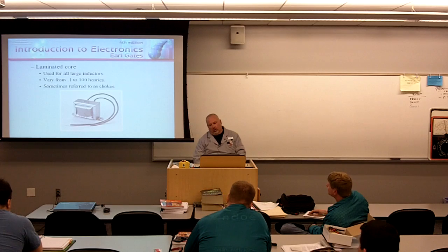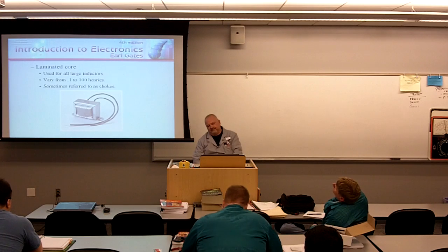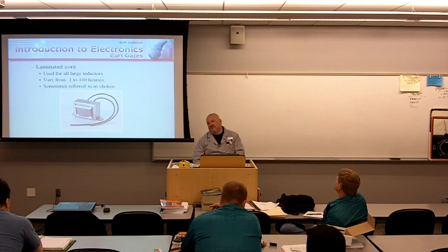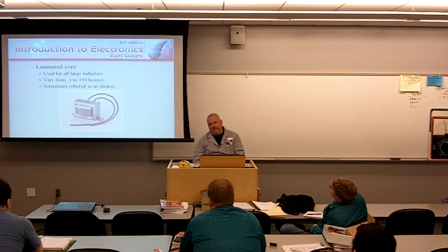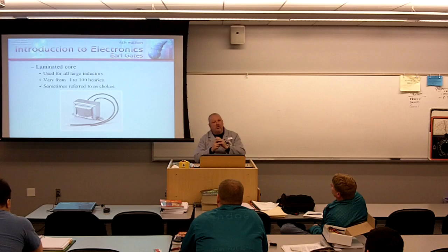This is a laminated core. And again, if you didn't know any better, you'd think it was a transformer. We know it's an inductor because there are only 2 wires coming out of it, and the top is stamped 4.5 Henrys, 4.5H. These can vary from 0.1 Henrys all the way up to 100 Henrys. This is also sometimes referred to as a choke. It's used as a choke in automotive applications and noise filters, meaning to choke off a change. It's going to choke the change.